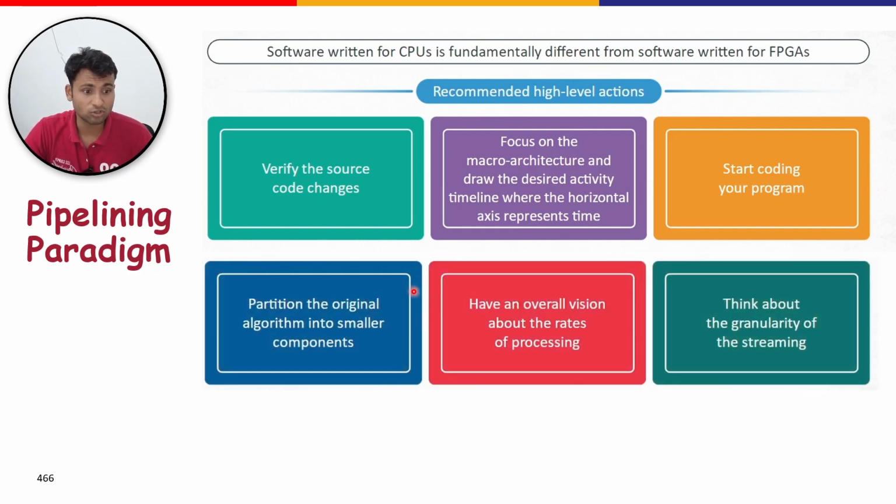Decompose or partition the original algorithm into smaller components that talk to each other via streams. Have an overall vision about what rates of processing will be required during each phase of your design. Think about the granularity and overhead of the streaming channels with respect to synchronization.